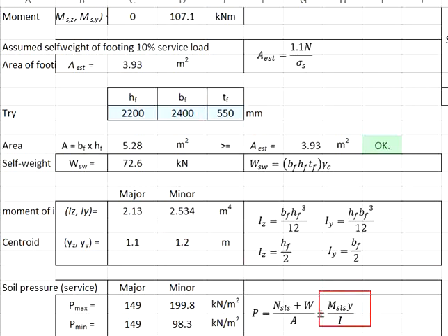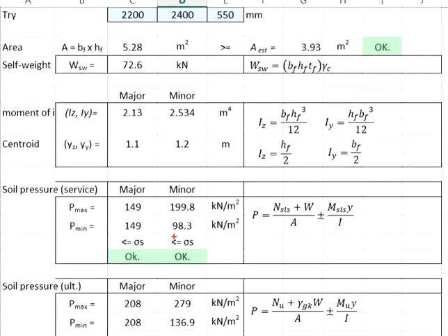Since the major axis does not have any moment, that means this whole thing will be equal to 0 in the major axis. Therefore, you can choose not to calculate the y and the moment of inertia in the major axis. Even though you calculate them, later multiplied with zero moment, the whole thing becomes zero. It will not influence the soil pressure in the major axis.